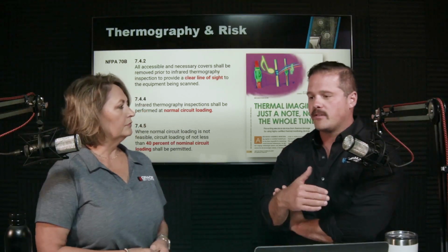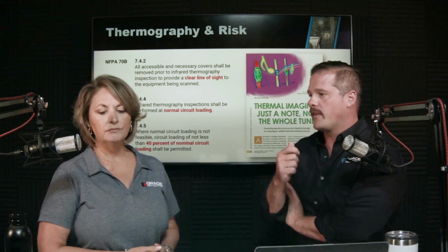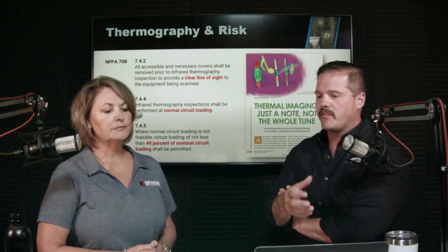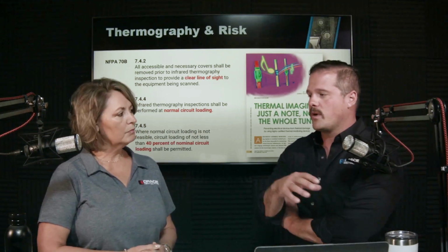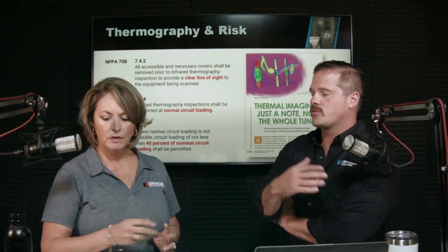So there are some areas definitely where thermography is the right tool at the right time. But there's definitely limitations on both the safety as well as the ability to really predict failures and get a trendable data set. Correct. In thermography, you can only see so much.